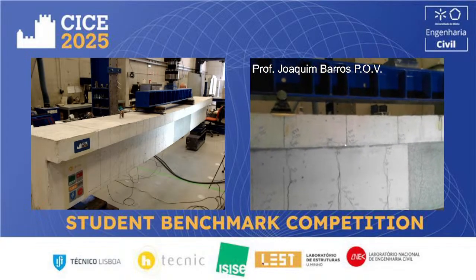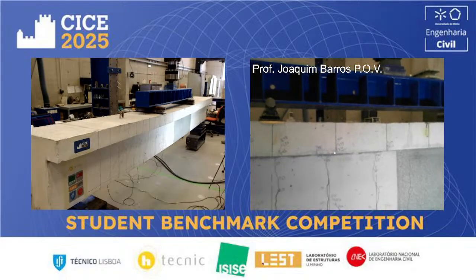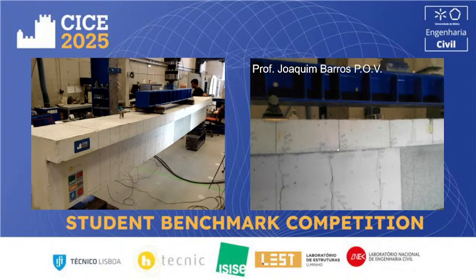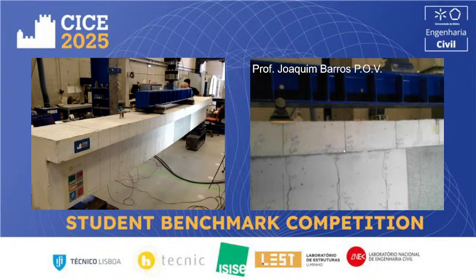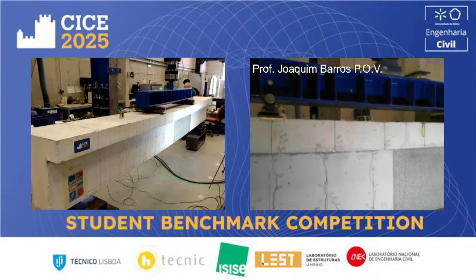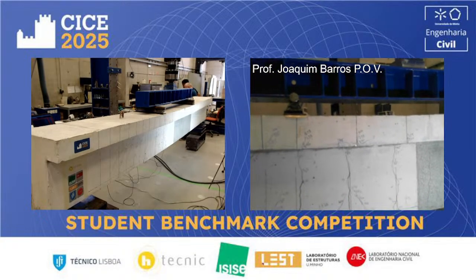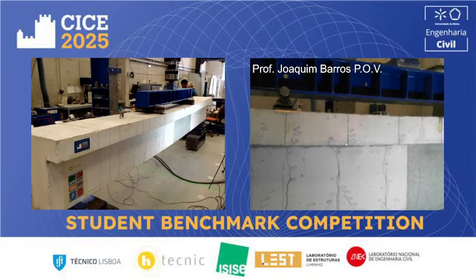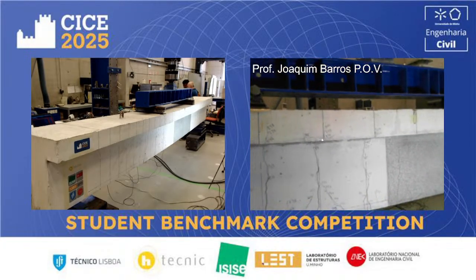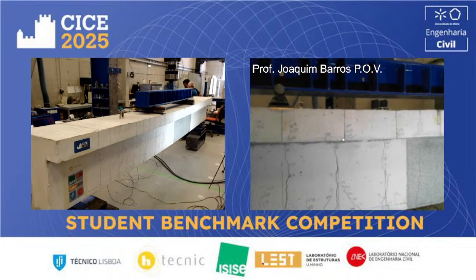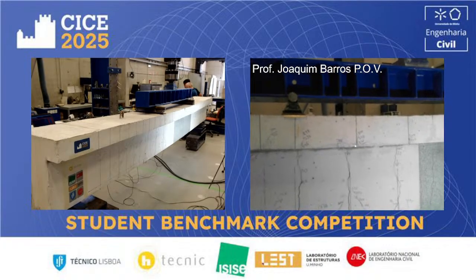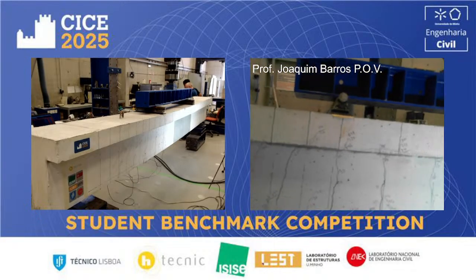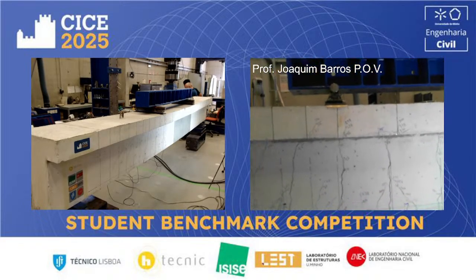It will be nice, after obtaining the moment curvature, and using the force method or displacement method, it will be quite easy to estimate the force deflection, even with a simple analytical model. Estimating the force deflection is relatively simple. Crack width and crack spacing is another story. It's much more complex.